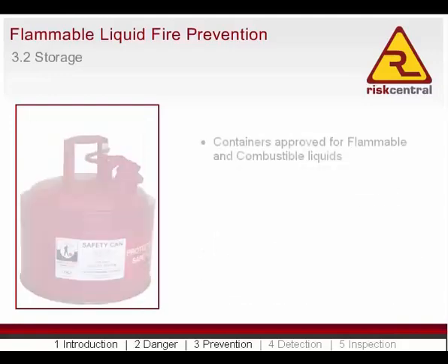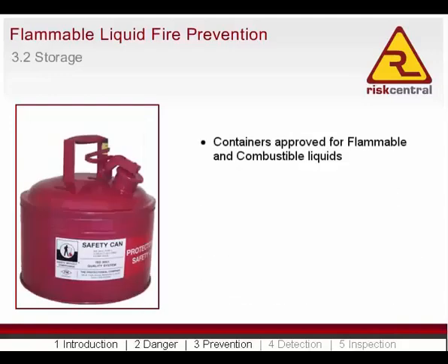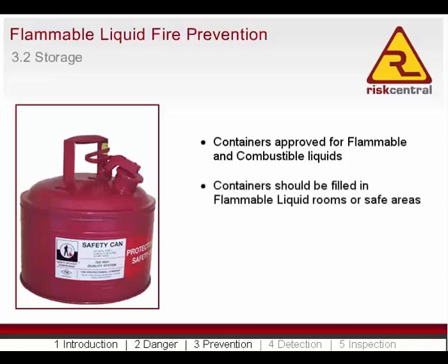All containers carrying flammable or combustible liquid should be approved for the intended use, that is, special flammable or combustible liquid containers. Containers should be filled in an appropriate storage room or in another safe area. All flammable or combustible liquid containers should be sealed when not being used, even if they are empty, as they will still contain flammable vapours.